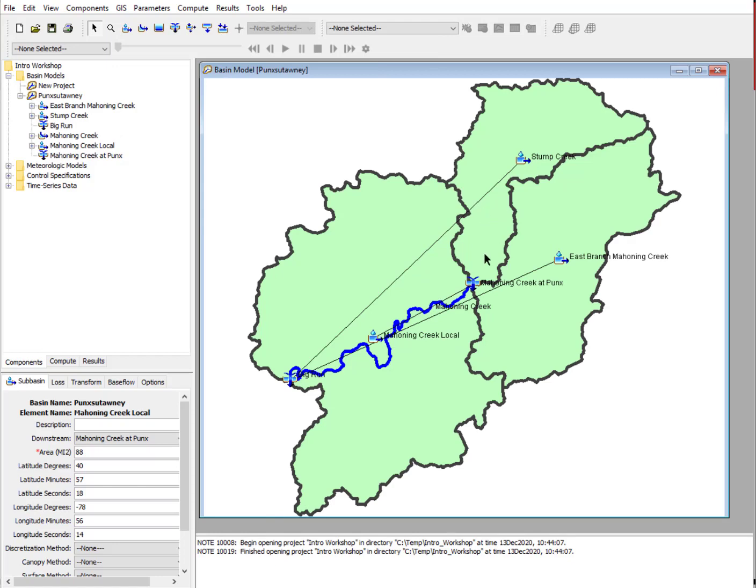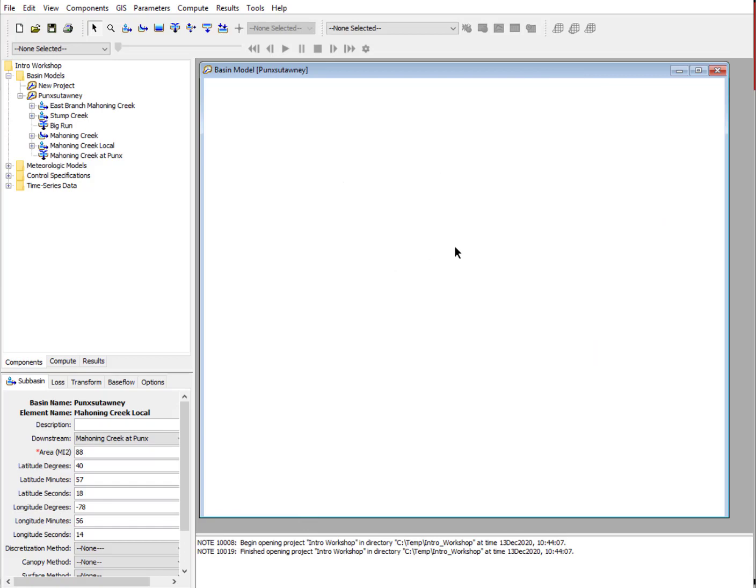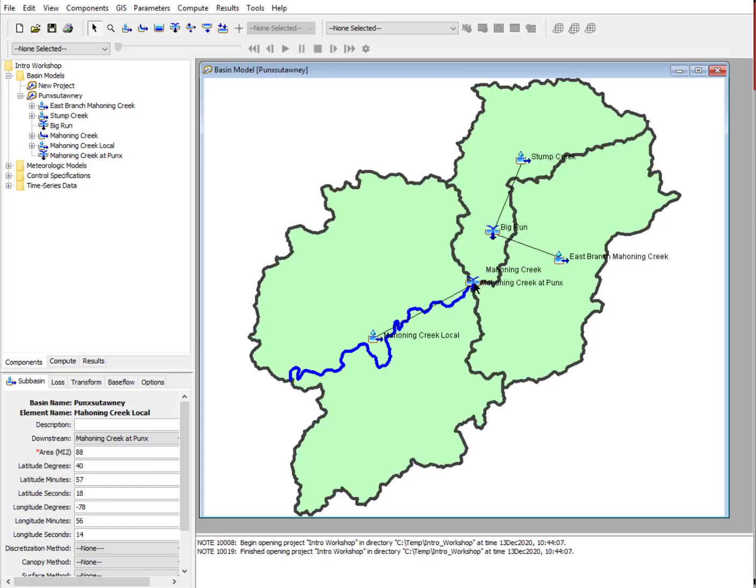What you might notice sometimes if you run through these steps on a different project is that the junction elements might be drawn initially in the wrong location. The elements are still connected hydrologically, they just might be located incorrectly on top of those reach elements. So I just moved them around right here.